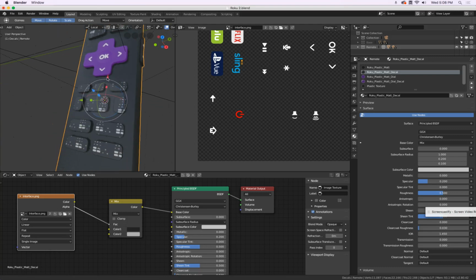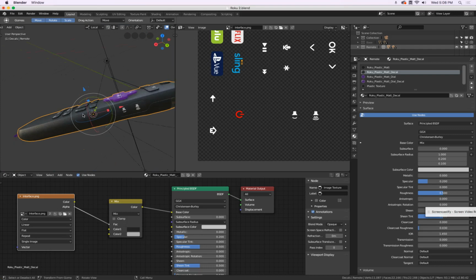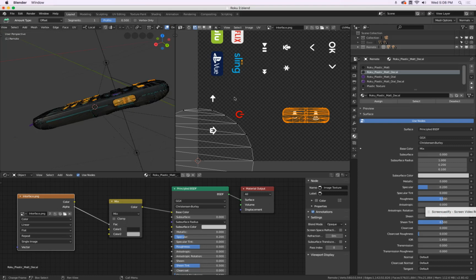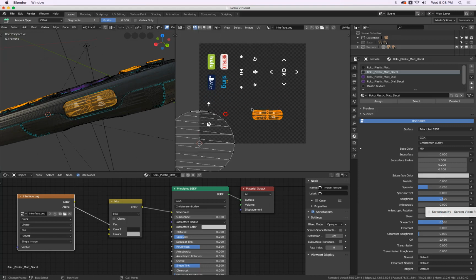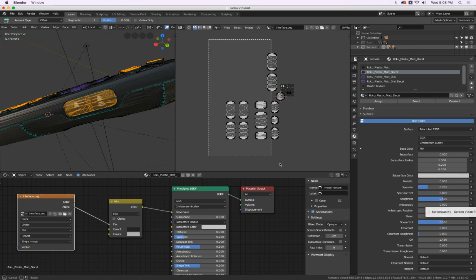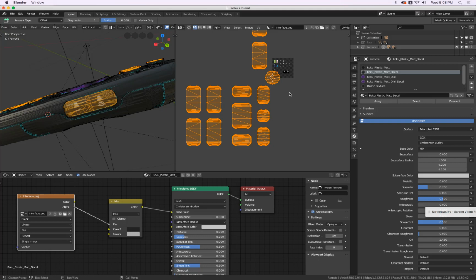So what's going on here? This looks quite interesting. So we have to adjust the position of these other buttons and also their scale. So edit mode. And then I say here, select. There are my other buttons. I will press here B, middle mouse button, or the scroll wheel. Drag, select. So this is out. And then all this is good, it's just too big. So I select everything at once. The spacing is also perfect.